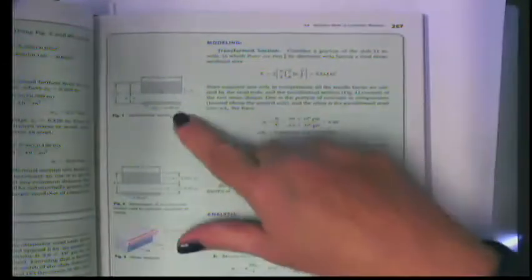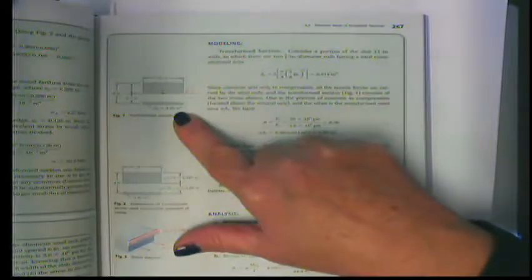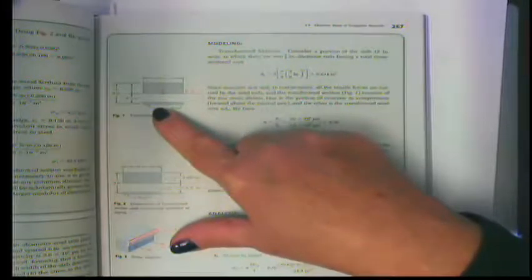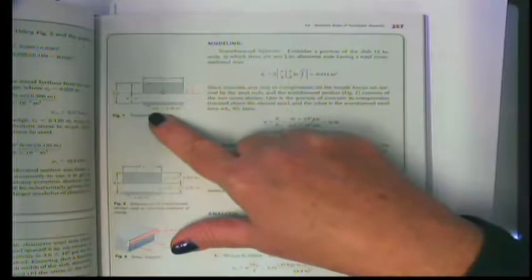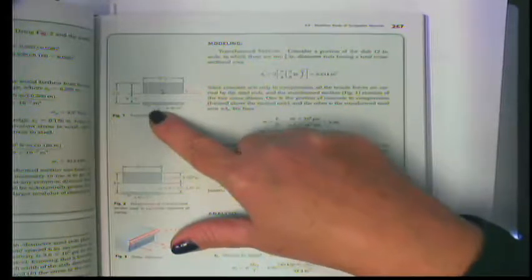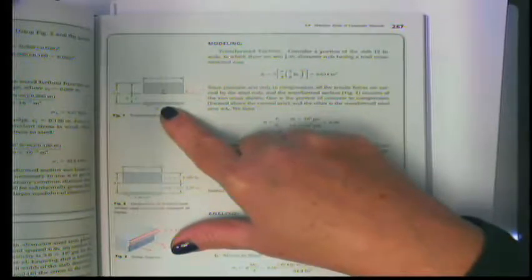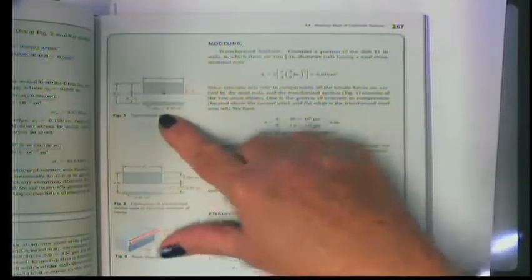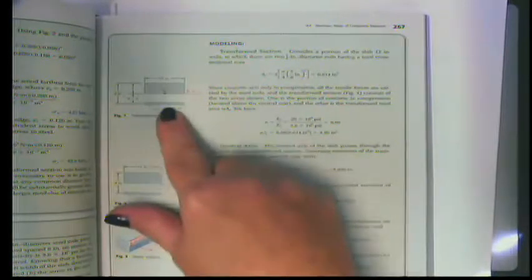All right, so how do we decide what this, we're drawing this piece, so this is a strange thing. This is the area of the rebar times the ratio of the moduli of elasticity, meaning that we're looking at the rebar as being a stretchier version of concrete. So we're saying if we had concrete that behaved like rebar, how much of it would we need in order to bear the tension below the neutral axis?